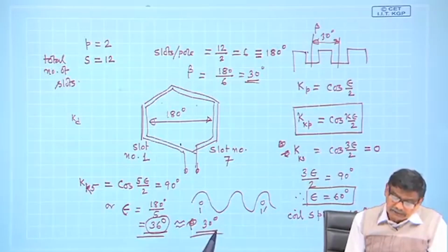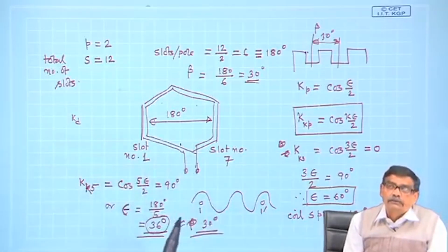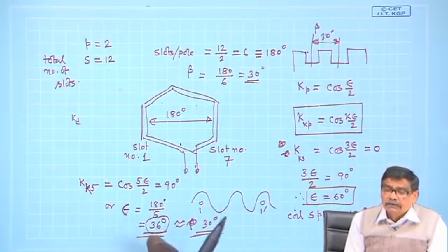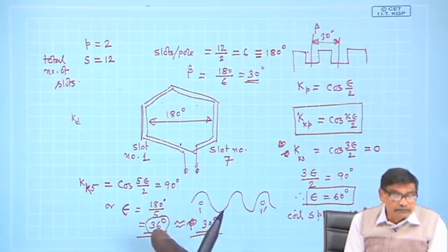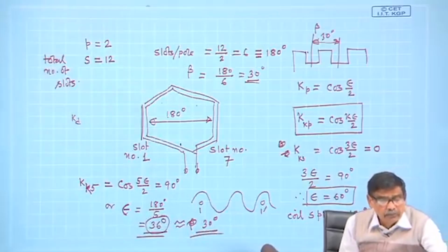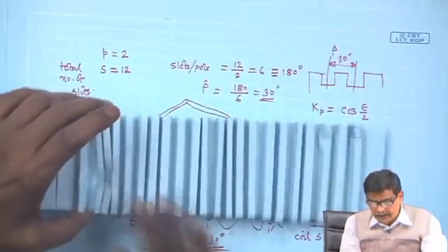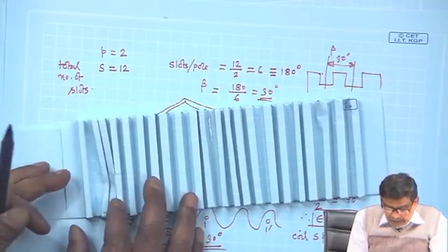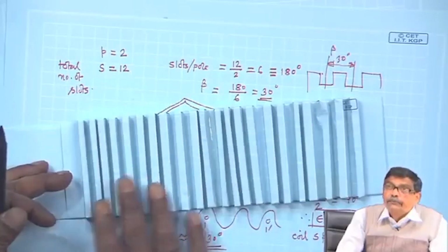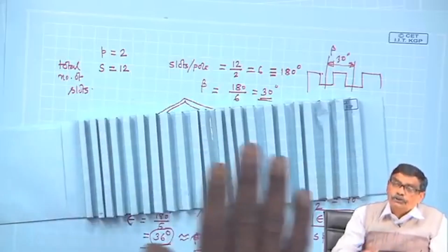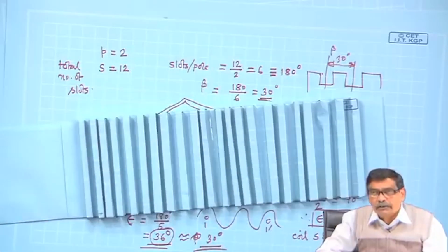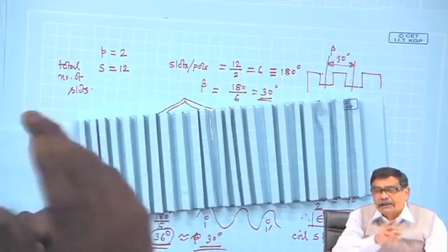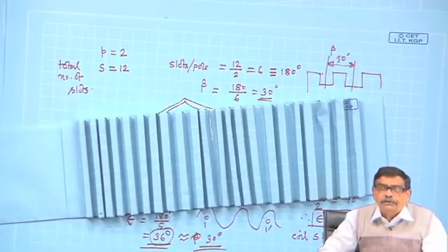Therefore, after studying these things, we conclude that it is necessary to distribute the coils. Distribution of the coils primarily means that you use more of the slots. That is one aspect. The second aspect is, if these coils are distributed, when they carry current, they will also produce an approximately sinusoidal B distribution, because a single coil gives a single rectangular MMF distribution or B distribution.